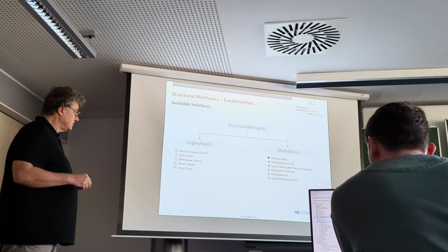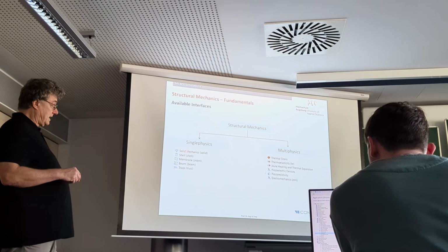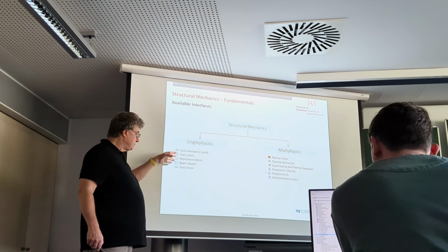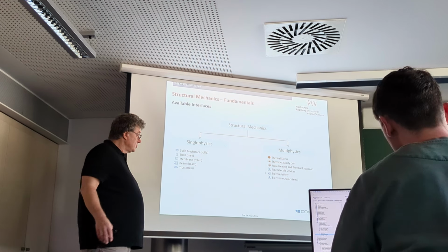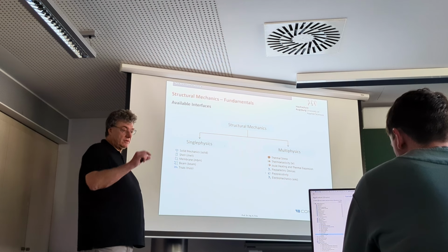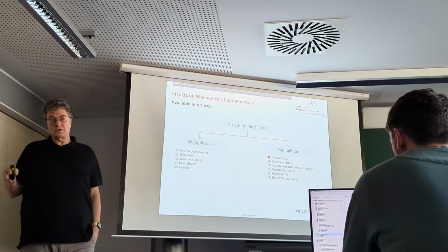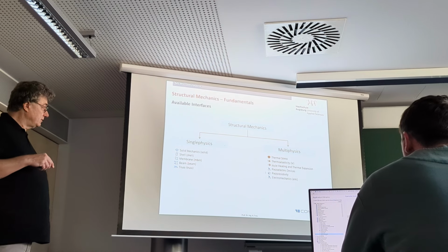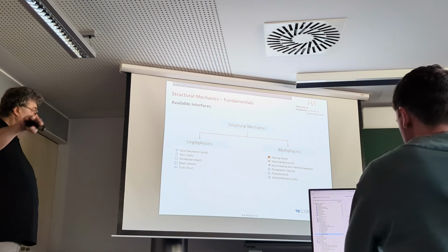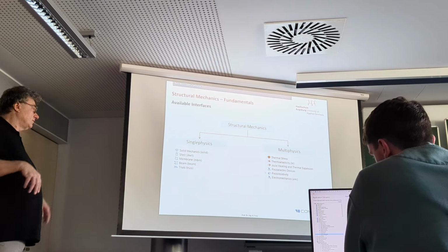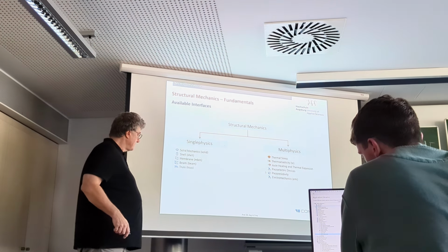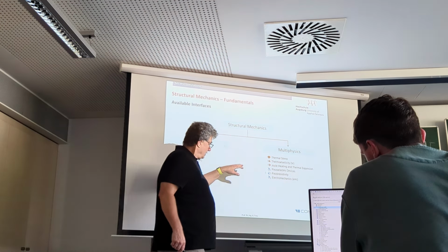So there we have single physics. Single physics in that case means solid mechanics, with some specialities, shells, membranes, so certain geometries which would cause challenges for the mesh. If you have a thin layer, you can mesh it, but that's not so easy, and COMSOL put here certain elements which actually neglect the thickness, so it's basically a 2D structure, but then of course they have to do certain things to take into account the thin thickness. Anyway, then we have multiphysics,